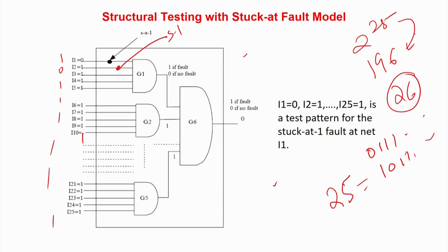This jump is very well established, because in the first work we said that we can do structural testing and still have very high correlation with functional test. But the problem was that you have to put a lot of multiplexing arrangements. Then we came here with stuck at fault models. Then we found that this number is also coming down, and more importantly we would not need extra pinouts.